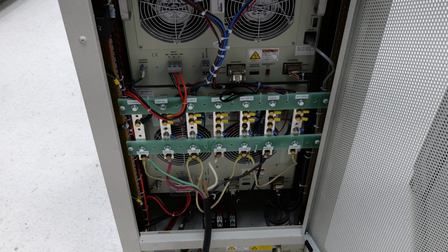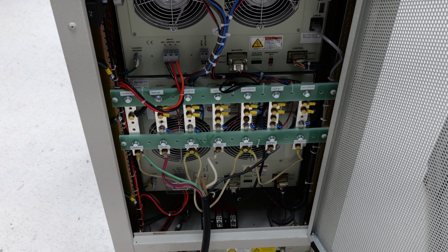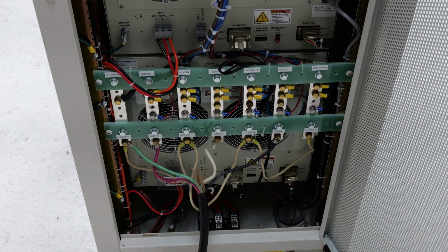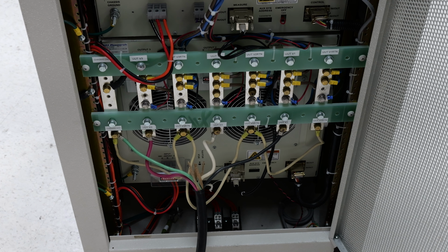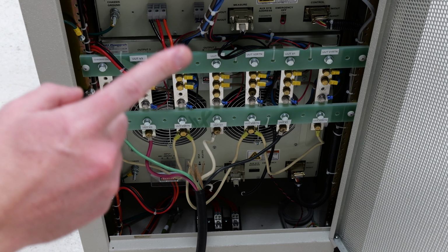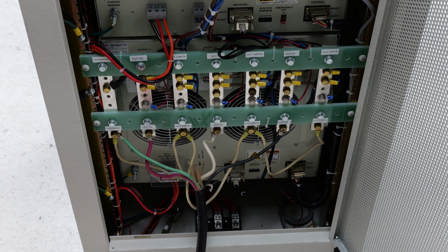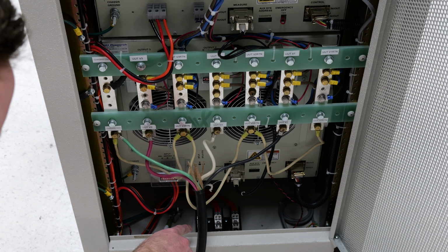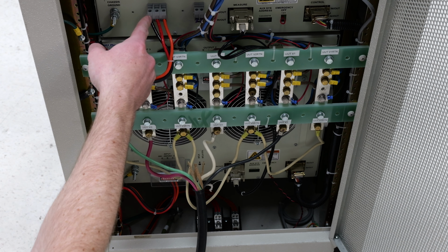On the back of the 9430-24, it all comes configured already to be put in parallel to get you that 24 kVA capability. The input power from your 480 volt AC mains comes in right here and is plugged in off the terminal block and powers both the units here and here.